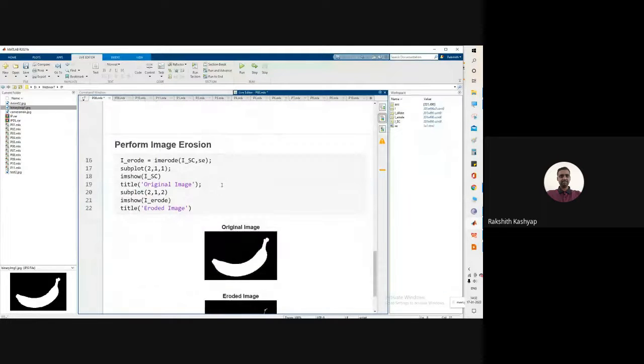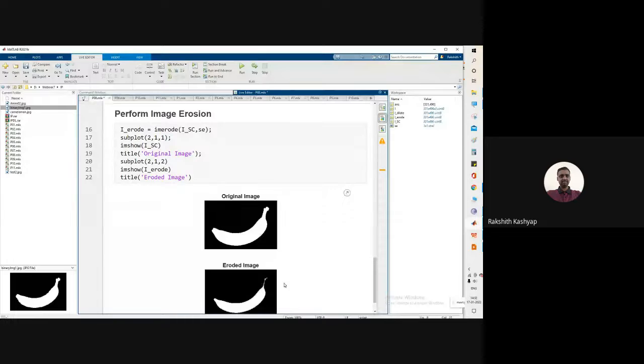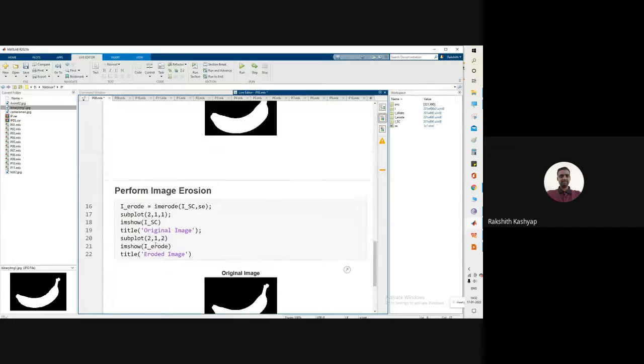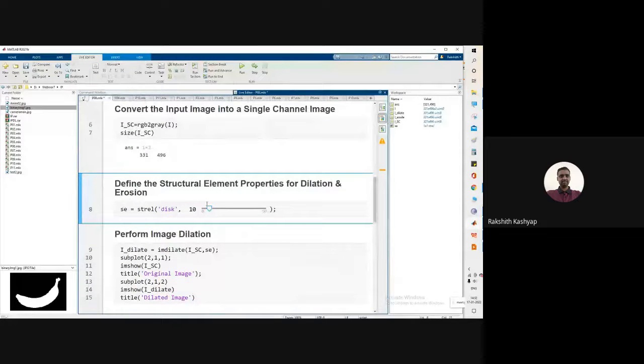Now if you go to the erosion operation, still we have the stock part. So we can increase the structuring element size a little bit more. Let me go to 11 or 12 as the structuring element size. We can do a little bit of fine tuning here. So let me go for 12 or maybe 13 also. That should not be a huge change.